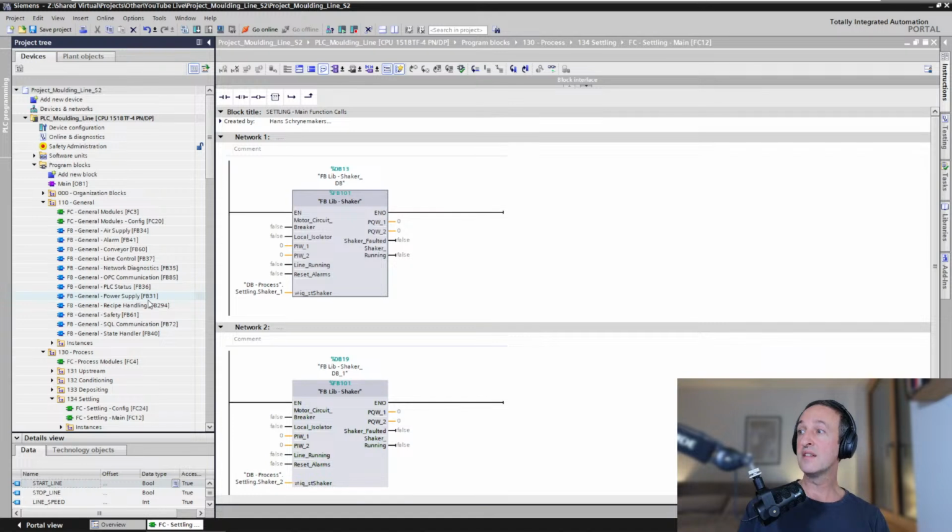I always untick these boxes because that's actually something that I was going to tell later, but I can just tell it right now. One last thing that I wanted to say is that I think you should only use global data in your HMI application. You should never have instance data coming as far as your HMI application.